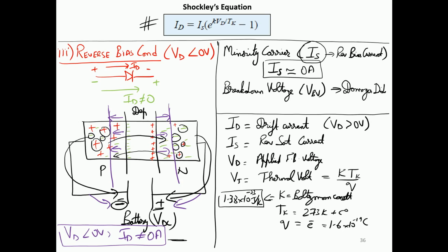And this equation basically represents the working of a diode that includes both the forward and reverse bias characteristics in the form of ID and IS. And finally, the value of N is called the ideality factor. Normally its value is between 1 and 2. Again, it is provided by the vendor.